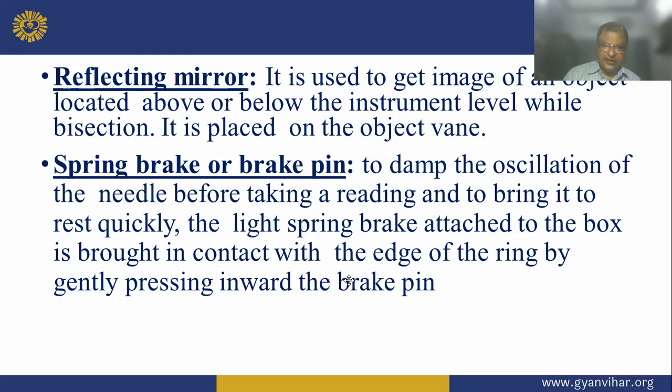So a spring brake or brake pin is used to damp the oscillation of the needle before taking a reading and bring it to rest quickly. The light spring brake is attached to the box and brought into contact with the edge of the ring by gently pressing the brake pin inward.